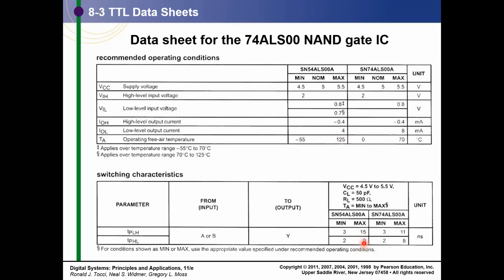You will see even for changing the signal from high to low, it takes slightly larger time. Though the best timings are the same, these variations are more because your operating conditions are wider. If you deviate from 0 to 70, then it might take more time. This is what it conveys. So we need to read the data sheet when we are using an IC for a particular application. We need to identify what parameters I need for my particular application, and accordingly I'll choose an IC.